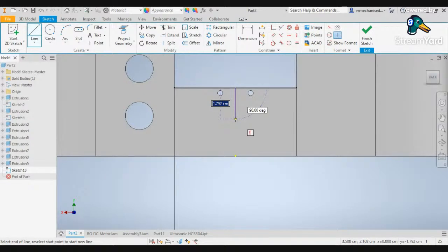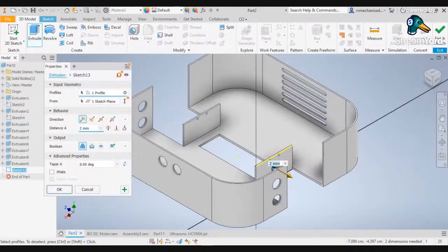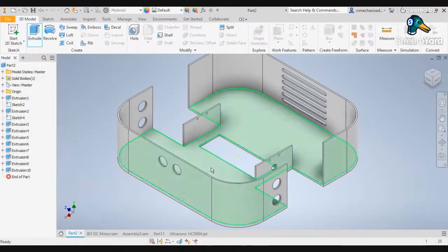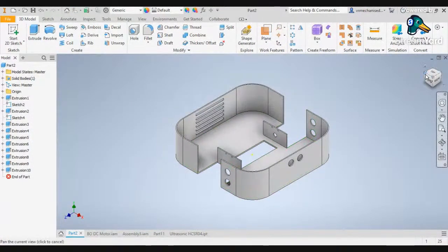Go for 3 centimeters. So it's type 2 centimeters. 2 centimeters. And over here now we'll be drawing a circle of around 1 centimeter, 1 cm. It's done. So click on it, and we'll be doing extrude cut over here. Extrude cut, done. Again, we'll be moving with this.